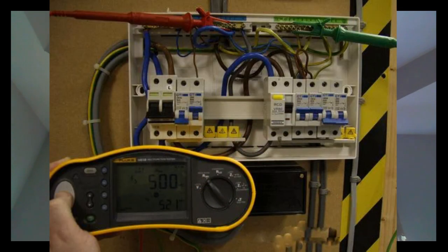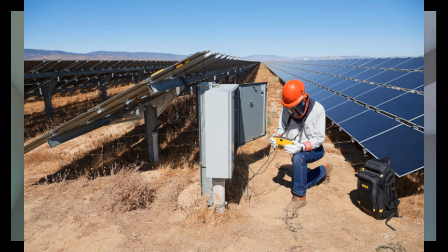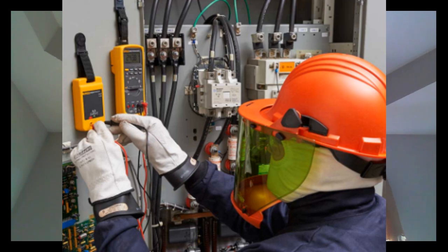How to use insulation resistance testing to find intermittent ground faults. Insulation resistance testing can be an excellent tool for identifying ground faults, including many intermittent faults. Before testing insulation resistance on any circuit with PV modules, contact the module manufacturer to check that insulation resistance testing through the module is allowed, so you don't void the module warranty.